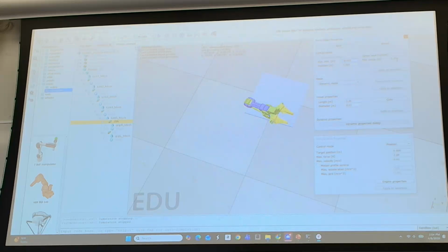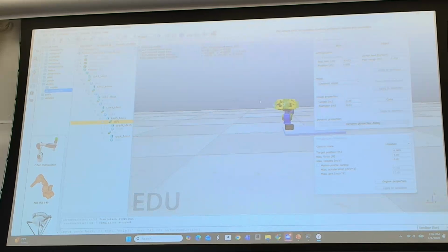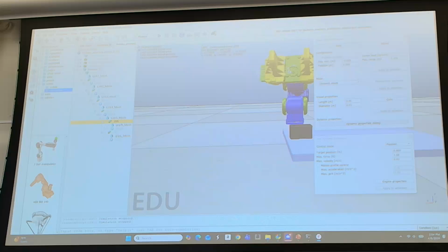Simultaneously, yeah. And by the way, for the prismatics, MuJoCo is probably the better engine to use. Otherwise, they'll tend to fly apart. ODE and Bullet don't tend to do well on the linear displacements. But you can see the prismatics moving backwards. It's sitting right here, we can go all the way out here, but this is the base. That's my zero point. You can go inward minus 0.025, but I can go outward by twice that.